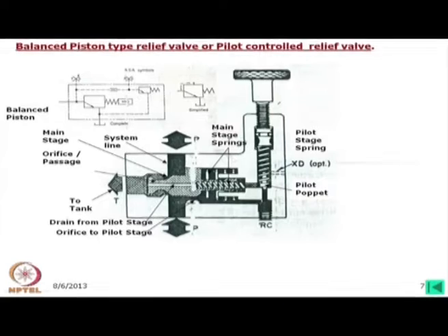If we develop the equations fully, we can understand how it is working, and for some valve we will definitely do that. But the difference between this balance type pilot operated pressure relief valve and the direct valve is this: there, direct pressure is opening the poppet; here, the differential pressure is opening this poppet.